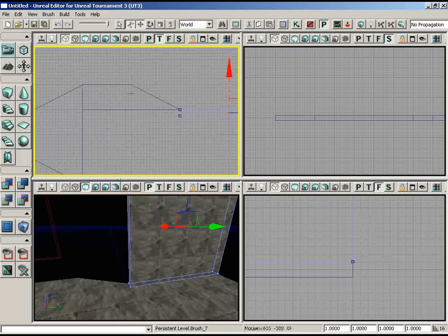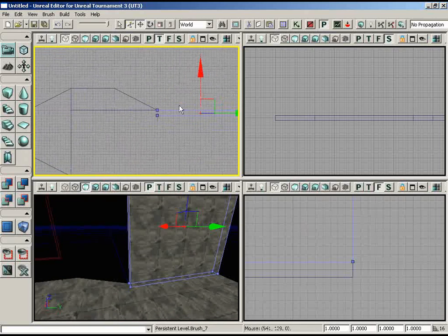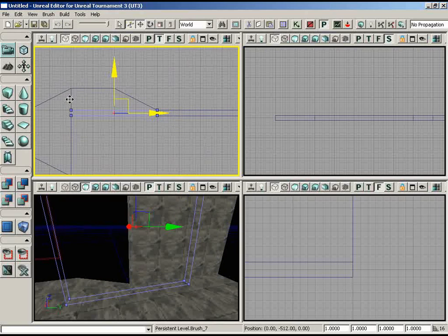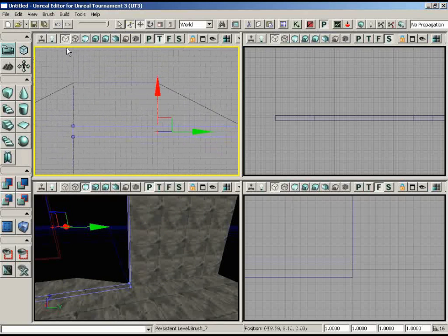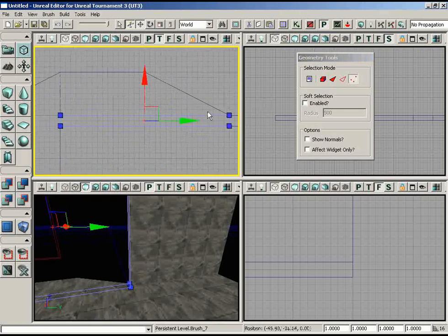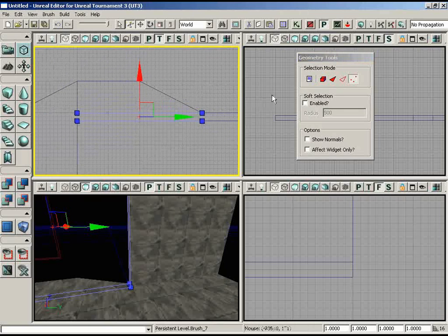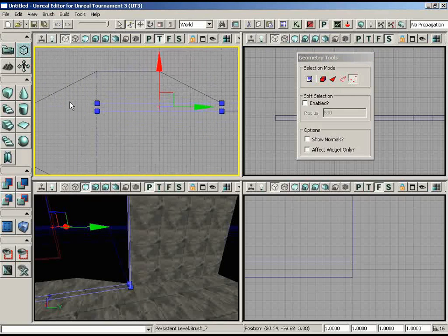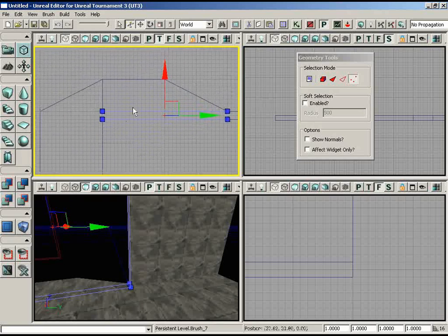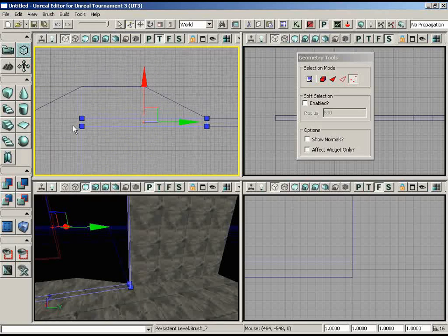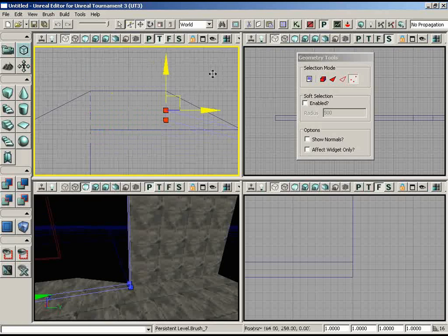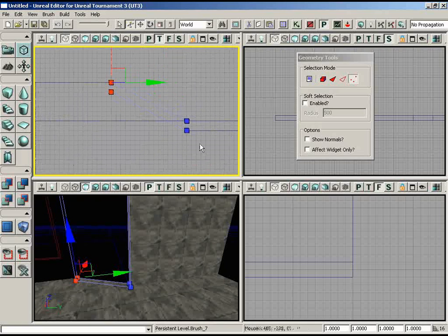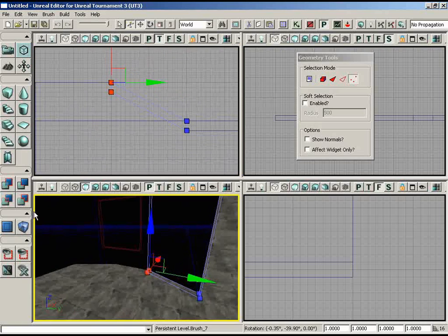Now I want to go along each of these edges and duplicate this over and move it into place. So for the first one, I'll do an Alt drag and line this up so that these two vertices match. And then I'm going to jump into geometry mode because I'm going to do this edge by edge almost. I'm going to stay in vertex mode because that makes the selections easier. So from the top view now, if we want to grab all these, we could do Control Alt drag a selection around those vertices, and just snap them into place so that they match this one contour.